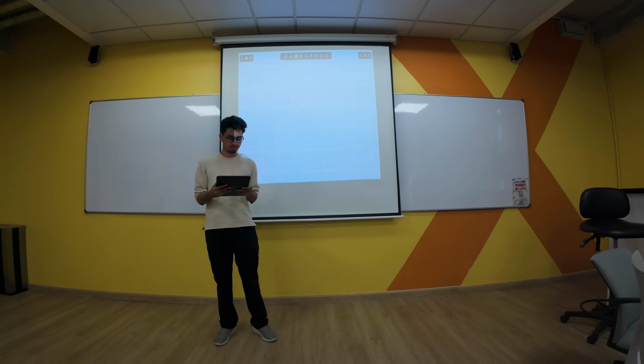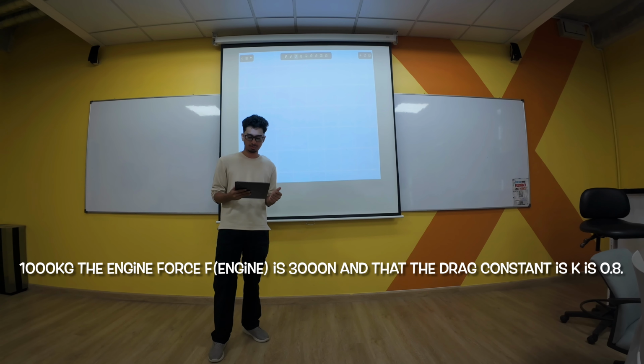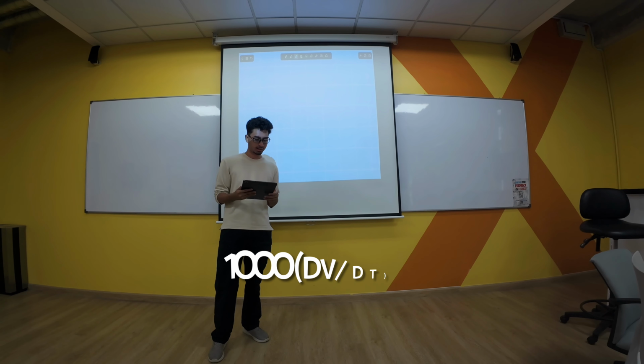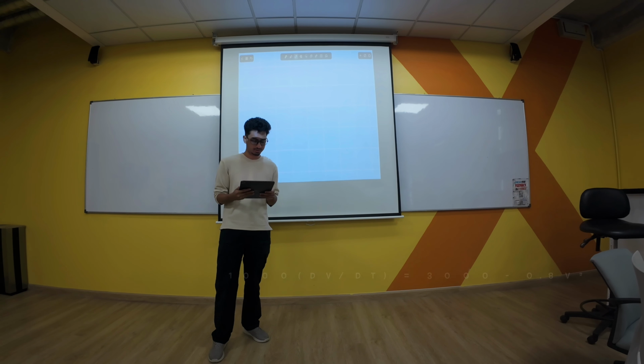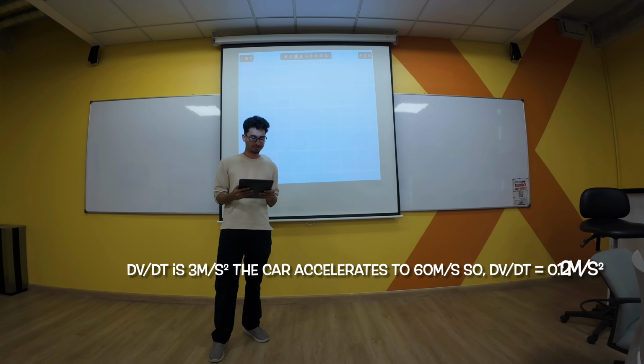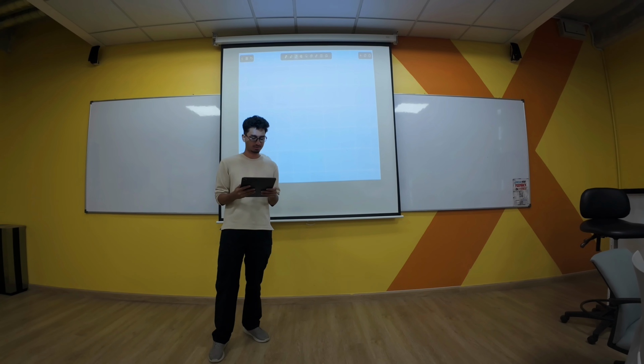Okay, so now let's try a real-world example. Let's assume the mass of the car is 1000 kg, the engine force is 3000 newtons, and the drag constant is k equals 0.8. We get the equation 1000 dv/dt equals 3000 minus 0.8 v squared. At first, v equals 0, and dv/dt is equal to 3 meters per second squared. When the car accelerates to 60 meters per second, dv/dt is equal to 0.12 meters per second squared. Now drag is almost equal to the force of the engine, so there is very little acceleration.